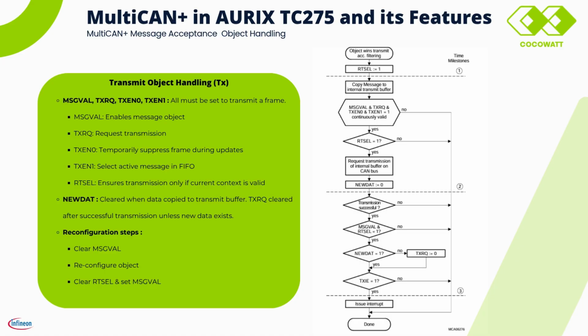The reconfiguration process is straightforward: clear message valid, reconfigure the object, then clear RTSEL and set message valid again. This ensures that the message object is effectively reset and ready for new data.